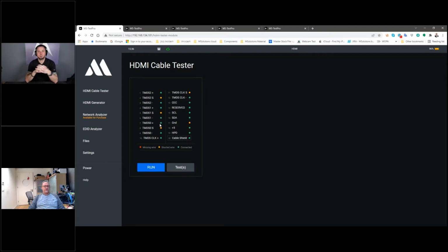In this situation, you can see that all 4 of them are shorted to the GND, but they are not shorted to the shield. This can indicate that this can behave well with one condition, that it doesn't get any noise from the power supplies here on the GND or any other interference, because the problem can appear if you have a problem with the HPD signal. The transaction might also flow up the GND and can interfere with the TMDS signal. This can create a video drop.